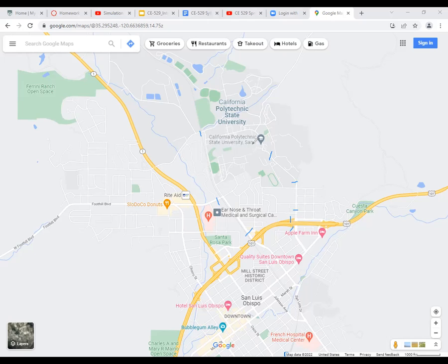But when you're building the model, you need to translate these traffic counts into what we call the OD flows, origin destination flows. Right? So what you really need, when you're building the model for a large scale community like this, a campus level model, is the same thing. Think about it at one intersection level. Let's say I'm just going to draw out one intersection here.